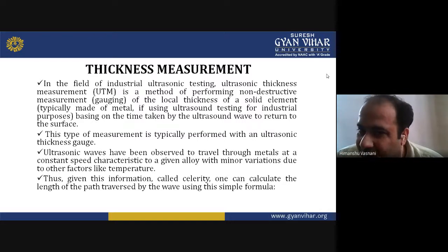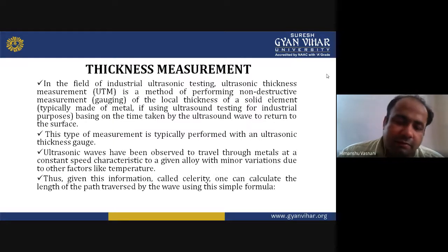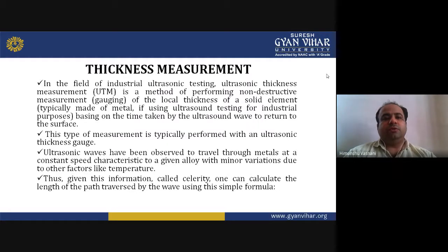Now here they are telling about the ultrasonic thickness measurement technique, where you perform a non-destructive measurement of the thickness of a solid element, based on the time taken by the ultrasound wave to return to the surface. So in this way they go for a thickness measurement.